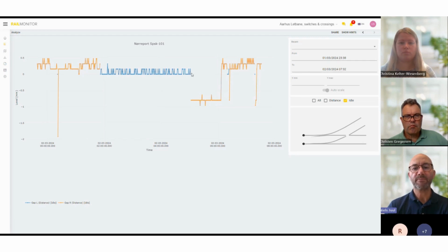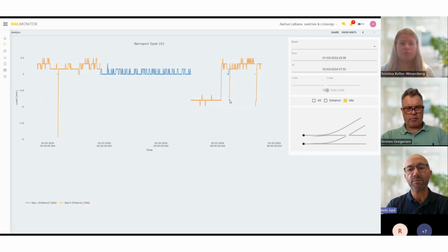And everything is okay. Then the rail moves to the opposite side, and the point machine actually leaves the blade in a minus position. And of course, it cannot be minus because you do not move the stock rail. But the blade actually tilts a bit. So there's a bit of tilting here, and then the first train passes, and it now moves the rail towards 0 again, and then it moves to the left side, sorry, and then it leaves again in a tilting position.